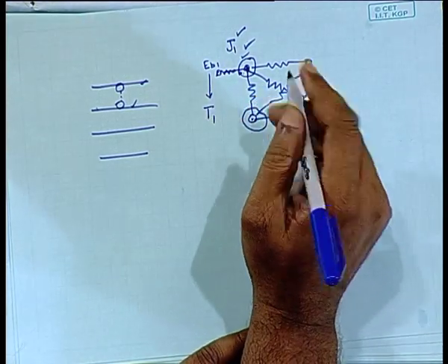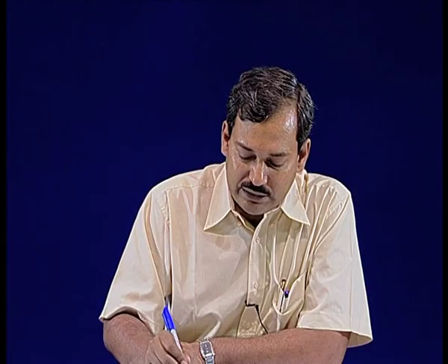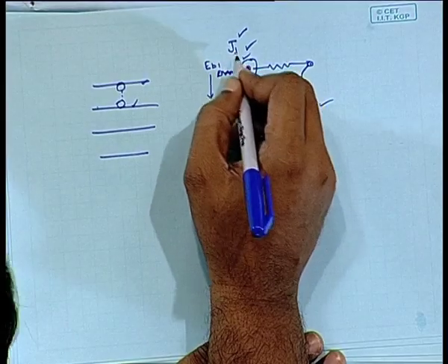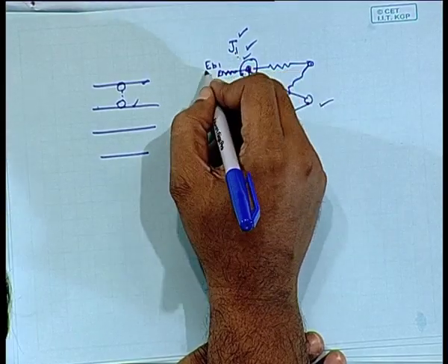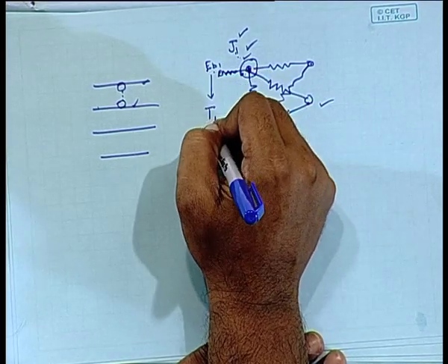So if we go beyond 3 surfaces, instead of using the network method, which is very easy to understand and can be expressed pictorially, you can simply write all the equations for each node and use the matrix inversion method to find the unknowns J1, J2, etc. Then knowing the radiosity of each node, you can find the radiation potential of the surface, and from that the temperature.